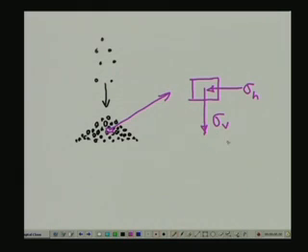We are going to consider this in greater detail later on, but what is sufficient at this stage is that sigma v is roughly equal to the weight of the soil, or weight of the particles, that are above this particular element, and sigma h is controlled by the lateral restraint of the grain movement.